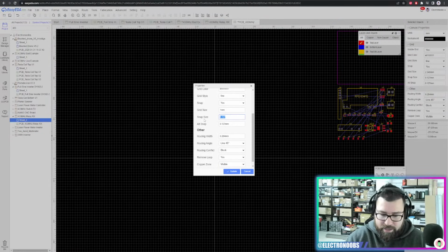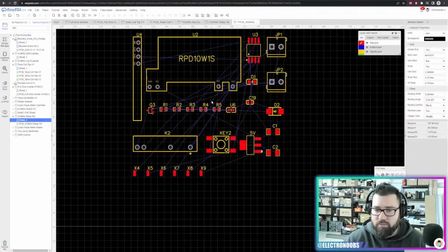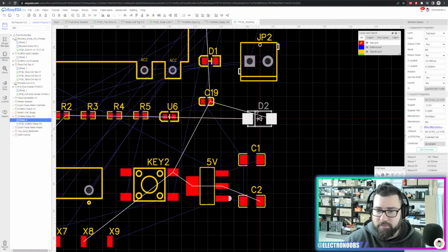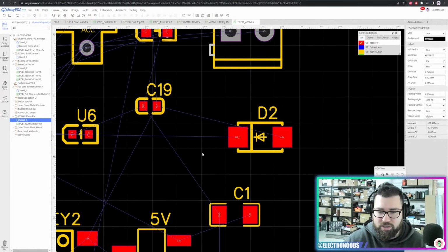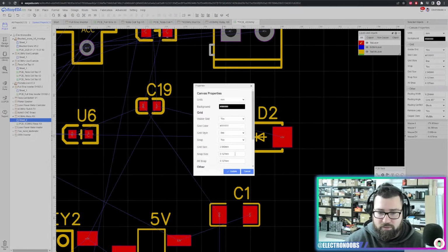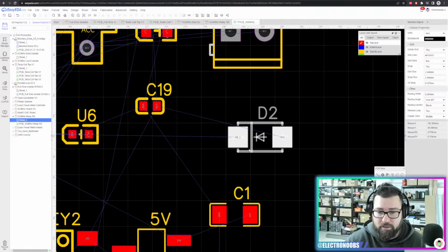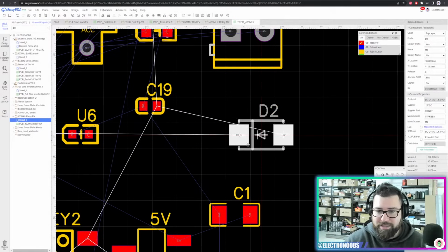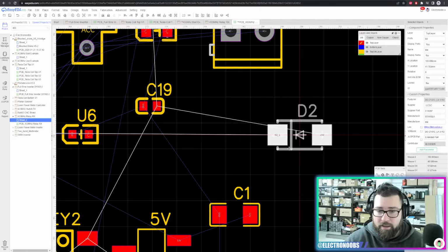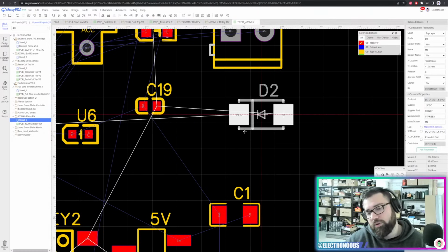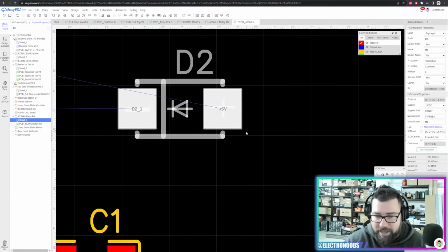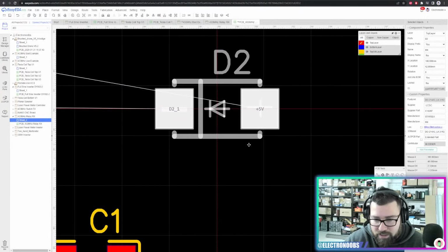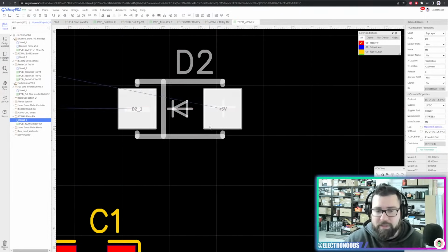And then the snap size. The snap size is when you move a component, as you can see, it can snap into place. Let me change it to a different value, just make it 2 millimeters. So each time that you move it, as you can see, it jumps 2 millimeters. So that's very useful, but you don't want to leave it at 2 millimeters because if you want to place it exactly here, you won't be able because it will jump 2 millimeters each time.